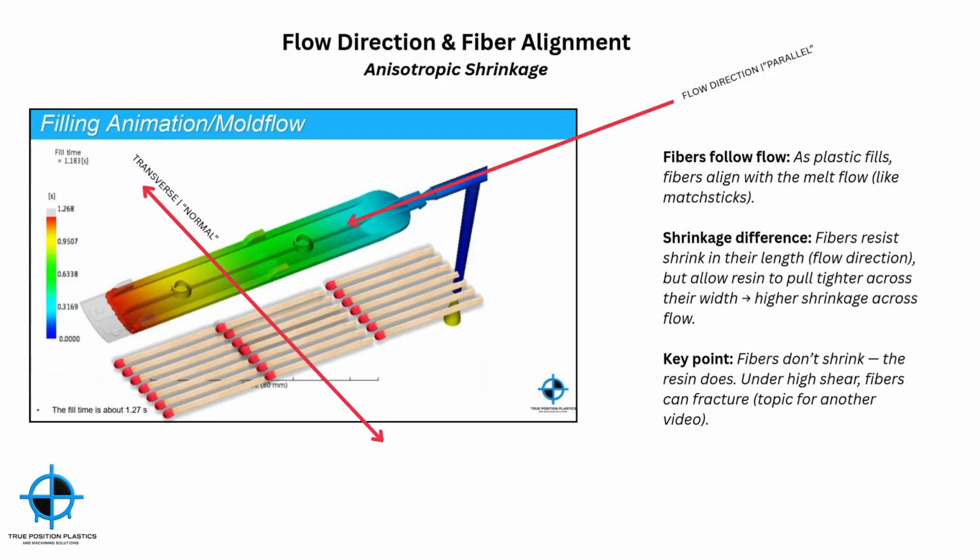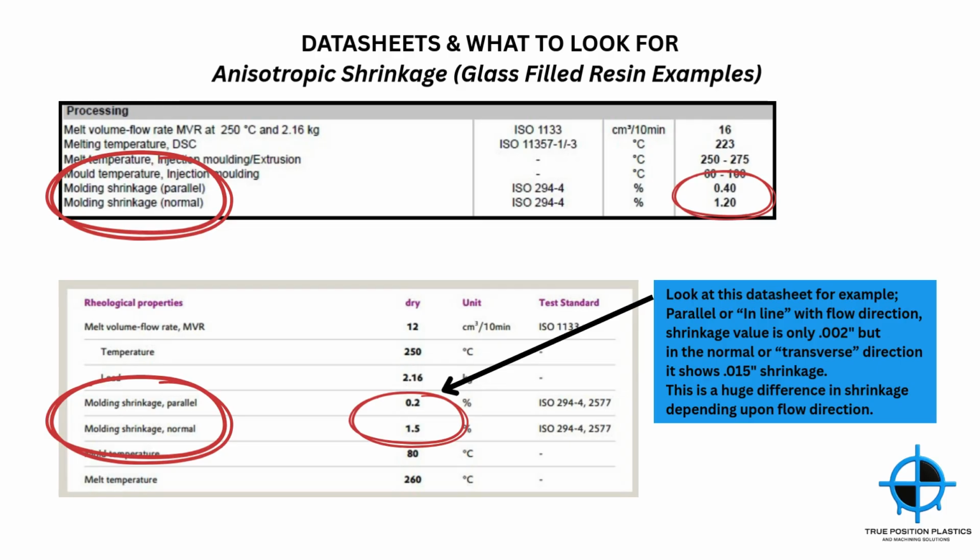So if a mold designer overlooks this directional shrinkage and just applies a single, average, uniform shrinkage value to a fiber-filled part, what happens? What's the real-world impact? Oh, it's detrimental. Ignoring anisotropic shrinkage isn't just a minor error. It's practically guaranteed to cause problems. It builds defects right into the mold design. The part simply won't shrink properly, and it will most likely never meet its dimensional requirements. This leads directly to major defects like severe warpage and distortion.